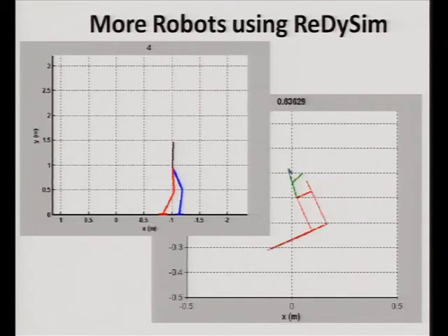When it is a tree type system, that cut does not appear. Like on the left hand side you have the planar walking machine. Now, it is a tree type system, so a cut does not appear, but in the right hand system you have closed loops. So, here you have a closed loop and there you have a closed loop. It is a combination of an approximate straight line generating mechanism, the green one, and the red one is the pantograph mechanism. Very interestingly, we have used it for a carpet scraping machine, but in Italy they have used it as a walking leg. Okay. So, I show its animation here.